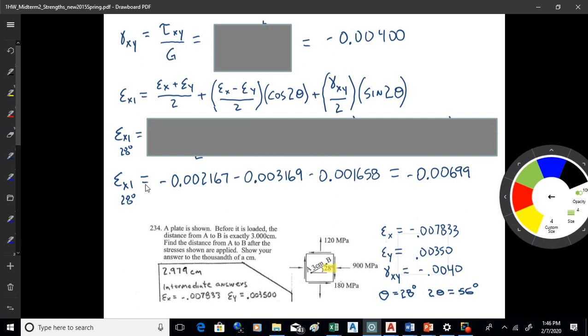That's actually the basis of some of the strain gauges they use. They put resistors, I think, and attach them to the material. When the material strains, the resistors change length, and that changes their properties. So when you're running a little bit of current through them, you get different output values. By reading those output values, that's the basis of a strain gauge, I think.